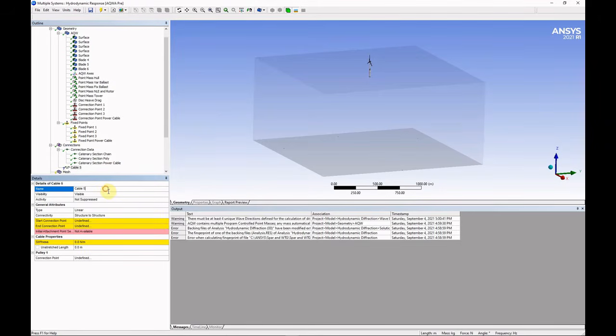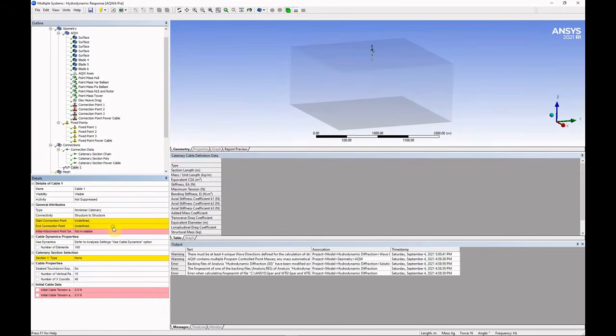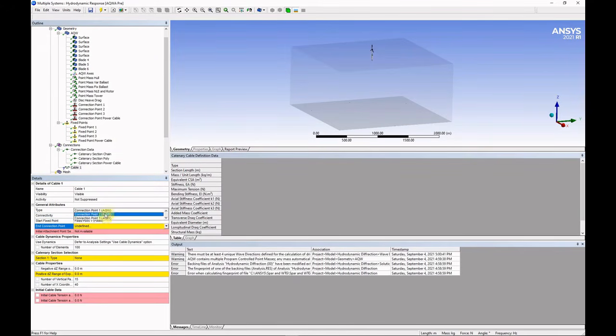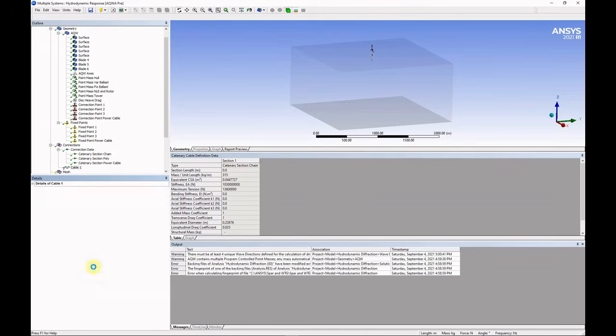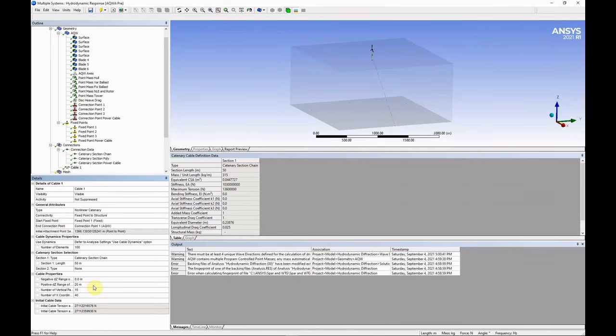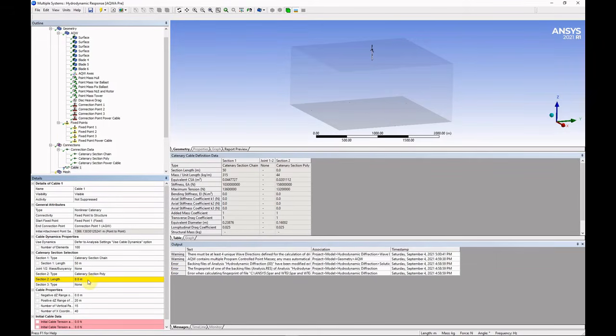Let's add nonlinear catenary cables. They are connected between fixed point on seafloor and the structure. These deep water mooring lines have short chain lines at bottom and at top. The middle section is the polyester line. Use the calculated initial length of polyester as it is going to stretch by self-weight.